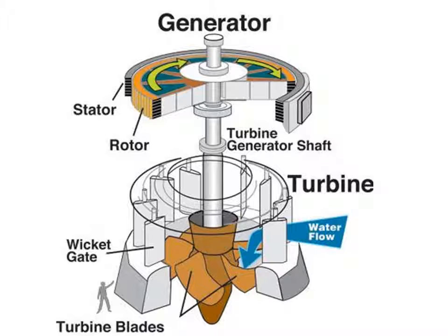The electricity generator works on the principles of Faraday's law, which states that a changing magnetic field can induce a current in a wire. In this generator, an electromagnet is created by wrapping wires supplied with DC current around magnetic steel, and these electromagnets are located on the outside perimeter of a large wheel connected to the rotor. As the rotor turns, these electromagnets pass by conductors located in the stator, which is not turning. This creates an AC current in the conductors, and this current is passed through a series of transformers before it is ready for the consumer.